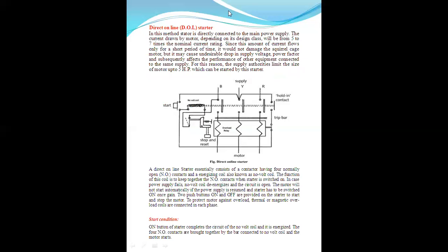First we will start with the DOL starter, or direct online starter. This is the general pictorial view of a direct online starter, and in this method the starter is directly connected to the main power supply. The current drawn by the motor, depending on its design class, will be from 5 to 7 times the normal current rating.